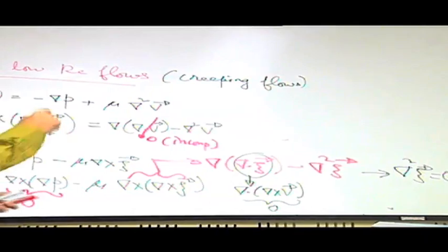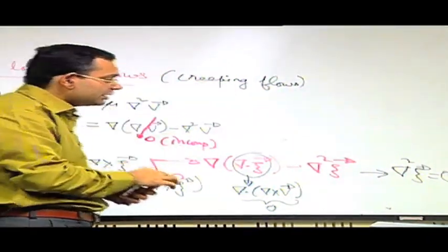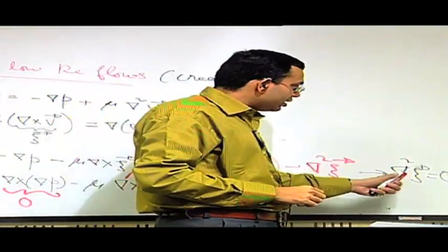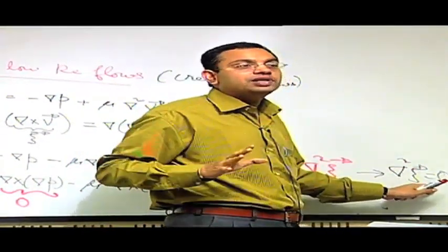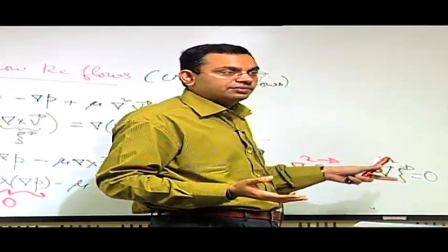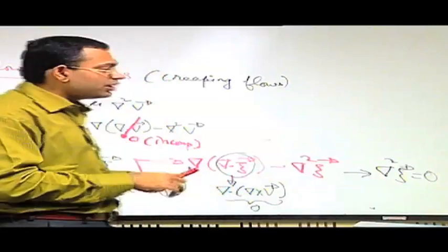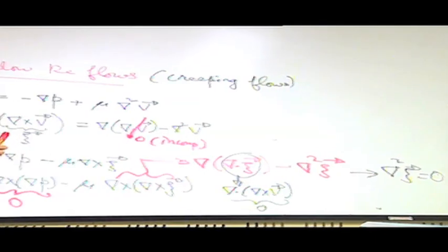Now, starting from this form, one can start with a velocity or a stream function and evaluate the vorticity as a function of that, so you get a governing differential equation which does not have pressure. In a way, what this has achieved is that it has just eliminated the pressure. So from this it is possible to get the velocity field. Once you get the velocity field, it is possible to evaluate the drag forces.